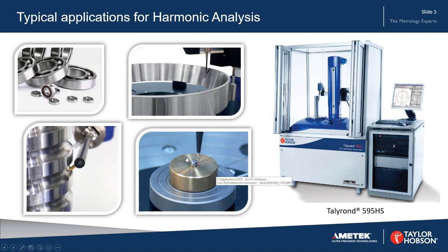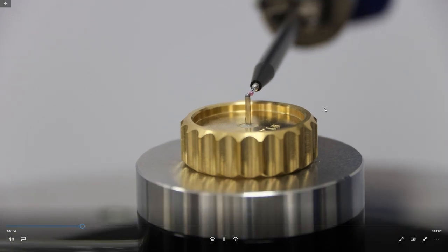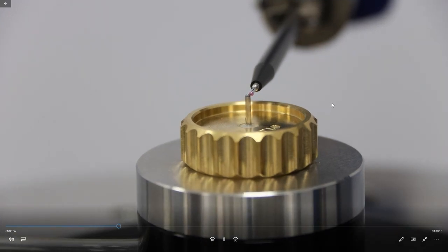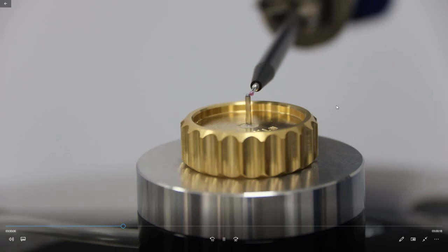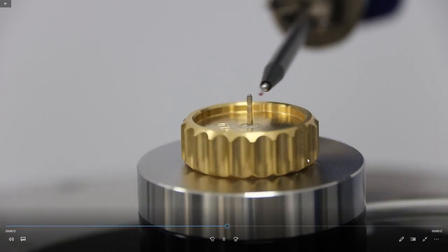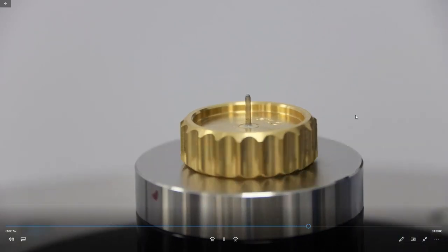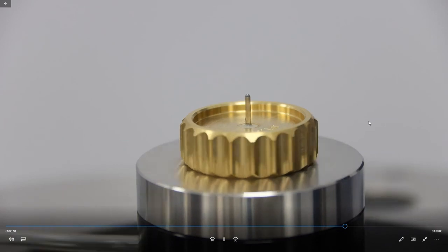Let's just have a quick look at the vacuum chuck holding the ball bearing as well. So this is just a very short video clip showing a 1 millimeter ball bearing held in a vacuum chuck on the Talyrond instrument, and we're rotating the spindle here at 6 RPM, taking in data, and when we've completed the measurement, of course, we would look at the harmonics.